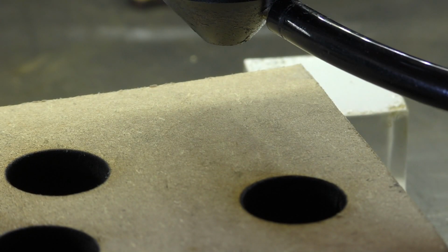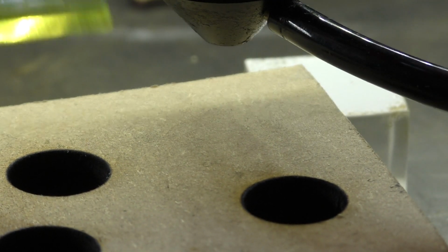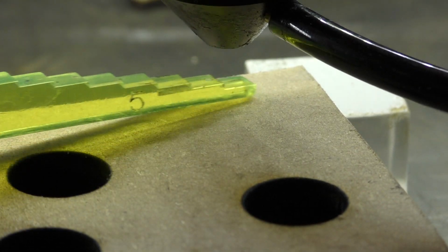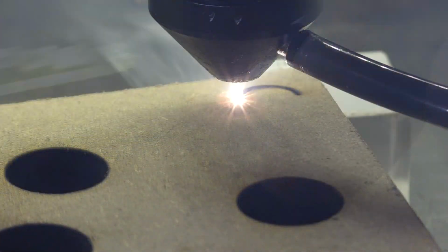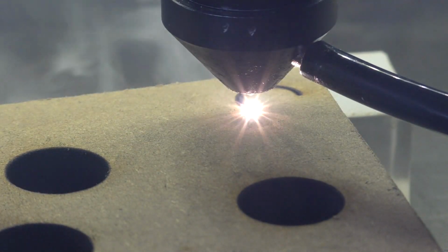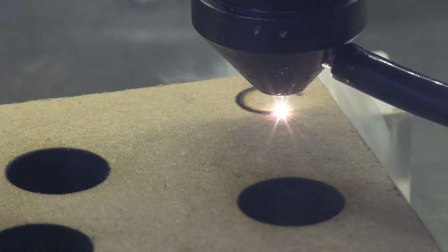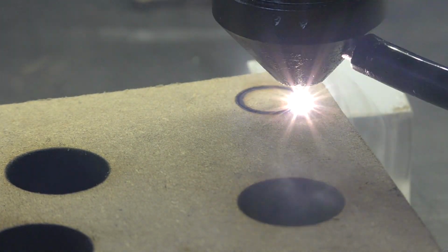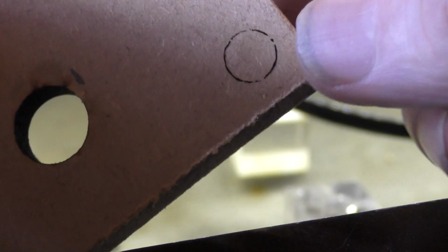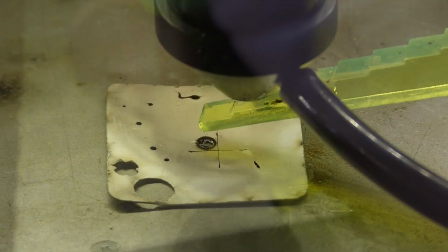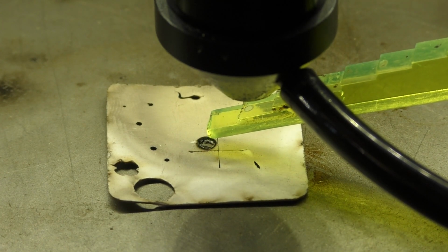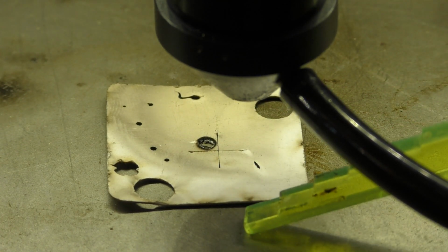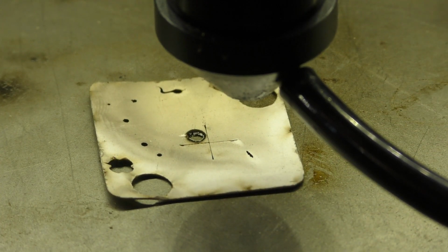Well, we're going to try this at 2mm a second. Again, you need to set this up to ideal focus, which is 4. The good news is the smoke is coming out the bottom. It has just about made it through, but that's 2mm a second. This is the burn on the 70-watt machine as the beam exits the bottom of the work. Let's compare that to see what it is on this machine.